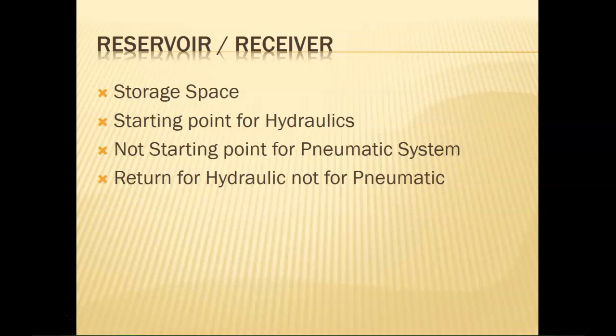Reservoir, receiver. You're looking at a storage space, and it is the starting point for hydraulics, but not pneumatics. Again, because with pneumatics, you don't always have to have one. But B, the fact of the matter is, with pneumatics, all a receiver does is store the excess so you don't have your compressor constantly running. It's kind of like a hot water tank, right? It's there because that stores and keeps the water hot.